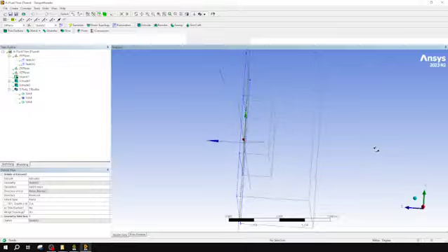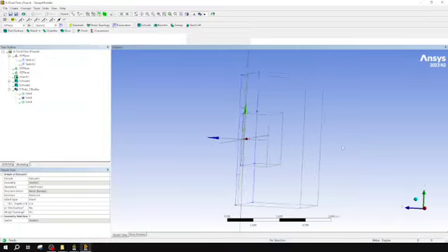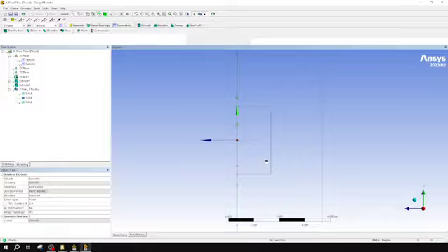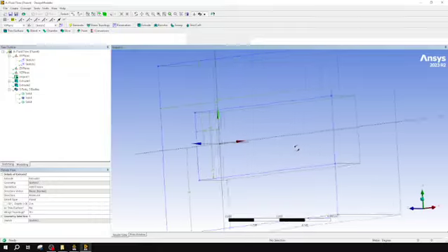If I'm looking out through the back, I can see that my wing ends about here, and I still have some of this refinement area to go. You will need your refinement box to extend past your wing so that you don't lose the tip behavior that might be going on with that.